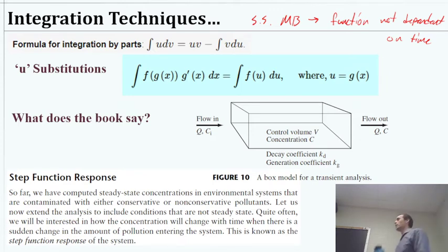And so in our batch reactor system, we do the integration and we end up with a time value. If it's first order, it looks like an interest rate equation, right? It's something times e to the minus kt, or we would substitute theta there. So it depends on that time. It'll keep going until we say, okay, here's the time we stop.